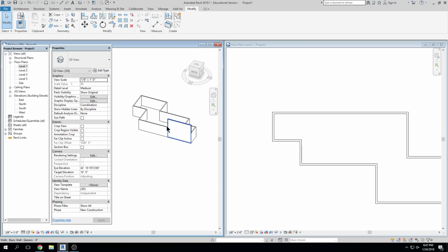We can get Revit to make things look like this, but it's not going to look quite right for us. We'll have some walls that maybe go like this, right there and there. We have little tiny short walls. But in general, when we're drawing our walls, we have a residence that we're doing first, so this isn't huge, and it's a one-level residence, so it's not a big deal. But the way our walls are going to function is our exterior walls are going to go from the lowest base constraint, wherever that may be, unless we have to change wall type, all the way up to the roof.